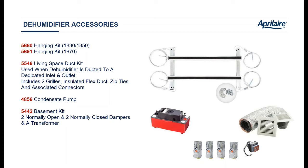We offer a living space kit, which is going to be the 2 grills you see and flex duct and some zip ties, so that you can have it dedicated into and out of a room for a remote installation. And then one of the more complicated installations is where you're actually dehumidifying 2 separate areas, typically the whole home, and then focusing on one specific area. You can use motorized dampers to do that. Again, uncommon, it's a problem solver. Don't think you're going to be installing it that way all the time.